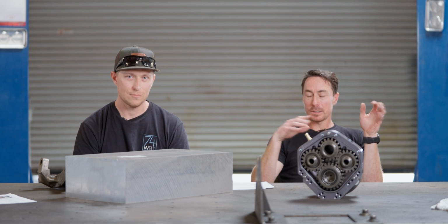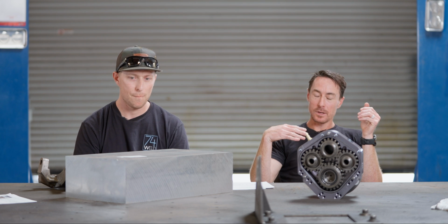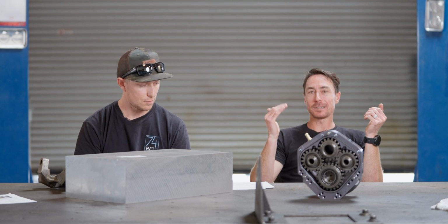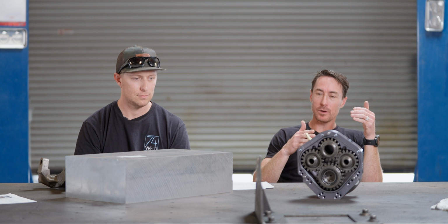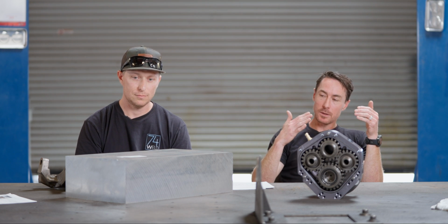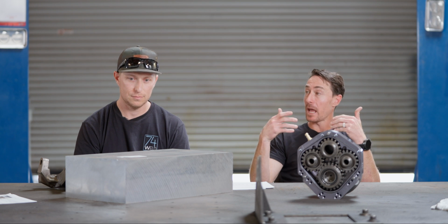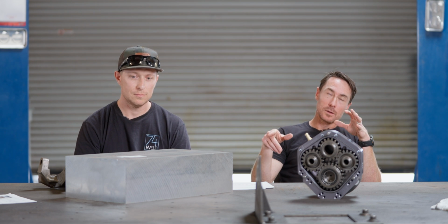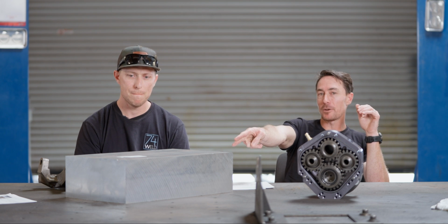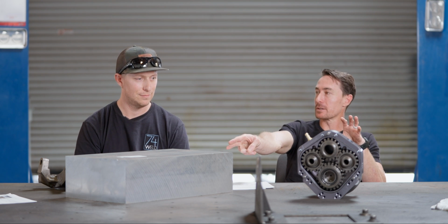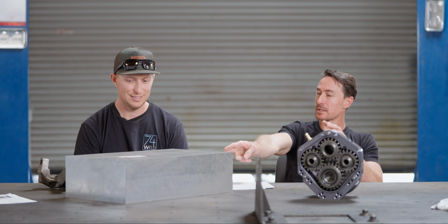It's an aging process where they take it up to a certain temperature, hold it there for a set period of time, slowly bring the temperature down. All of the 7 series alloys are aged, where, I might be wrong on this, hopefully somebody corrects me in the comments, they're going to hold this material at like 120 degrees for 48 hours to age it back to a T7651.